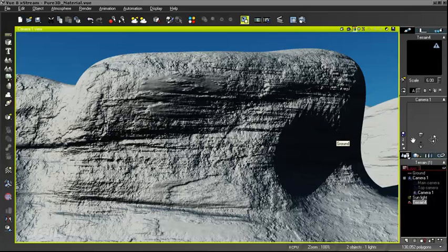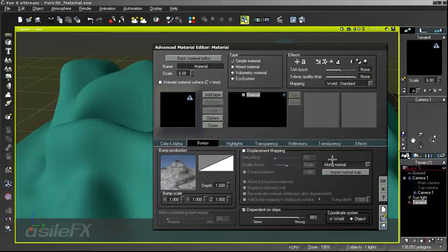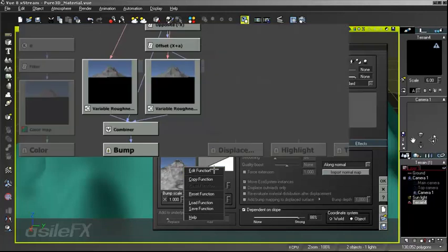And just going back to the render, another thing I want to note is that for very fine details and this roughness, well, we're mostly going to be getting rid of it, but you do want to avoid those being below 0 for the number output, because the displacement going inward is going to cause more problems than displacement outward. And without an inward displacement, it's just not going to look right, because you do have the ability to displace outward only, but I've found that it just doesn't look as good.